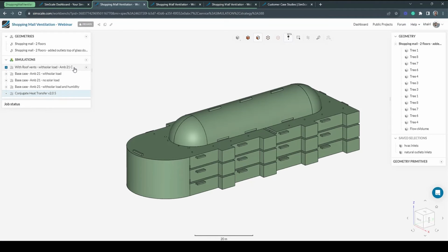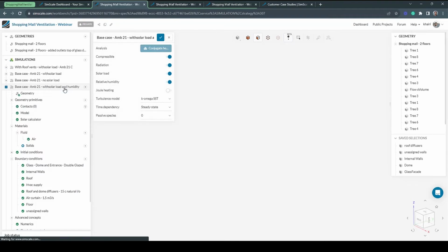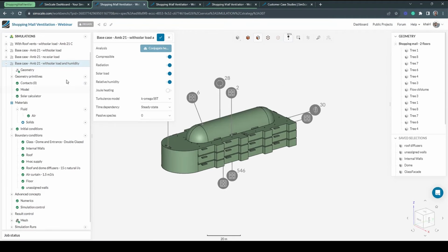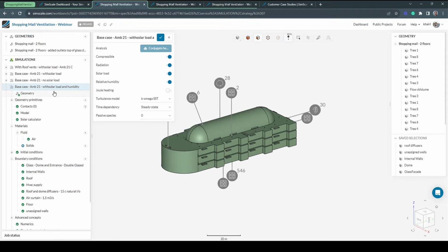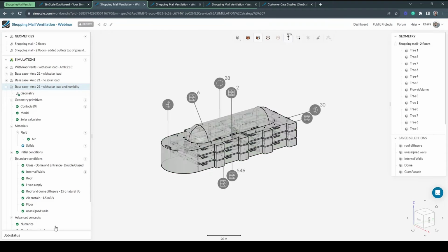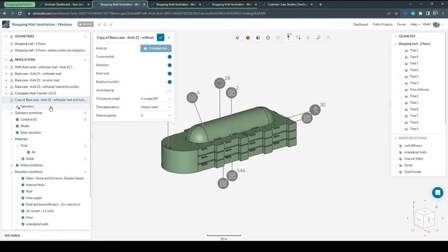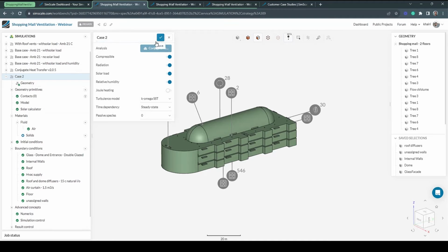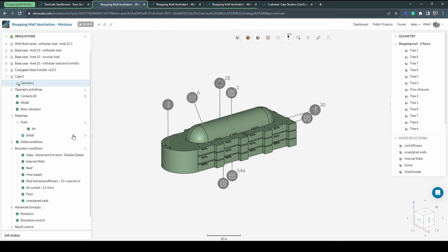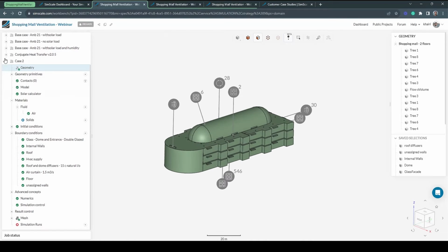And to set up for this, what you can also always benefit from is the fact that you usually don't need to set up a new simulation from scratch. If you have a template, let's say, of one simulation that you've run, and you know the setup is going to be used the same for the new modified design, but you're just changing the geometry, you can make use of this template that you have here, duplicate it, and then change the name and finally change the geometry that you would like to simulate, and then go ahead and run that simulation.